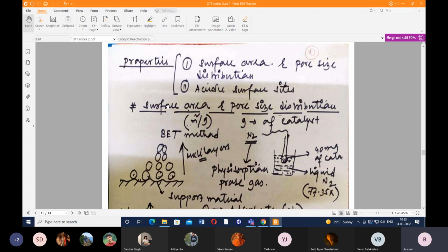At that temperature, activated carbon will burn off in the form of carbon monoxide and carbon dioxide. That's why people generally use non-carbonaceous support material to avoid such burn off issues, since non-carbonaceous material has a high melting point above 1000 degrees Celsius, so the burn off issue is not there.